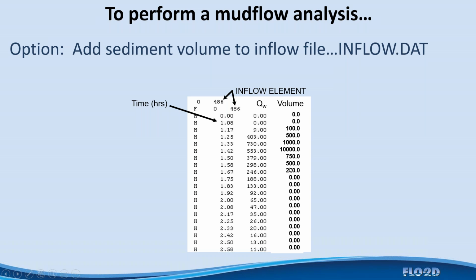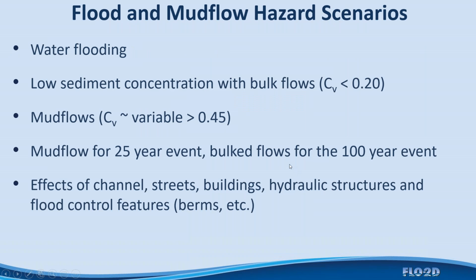The model would recognize that if it's less than 1, it's a concentration by volume, and if it's greater than 1, it's the actual volume in either cubic meters or cubic feet of sediment. And that's solid volume, not volume that's sitting on the ground with porosity, but a solid volume of sediment. So when you do these mud and debris flow flood hazard simulations, I would recommend that you provide